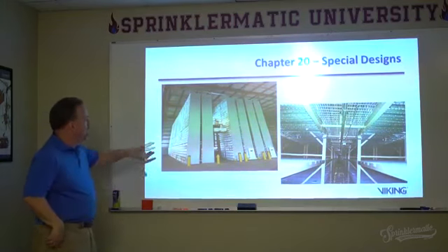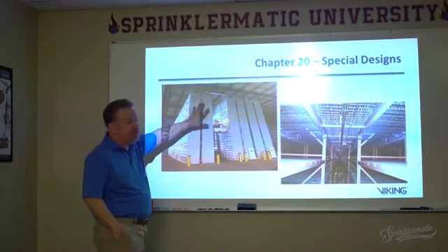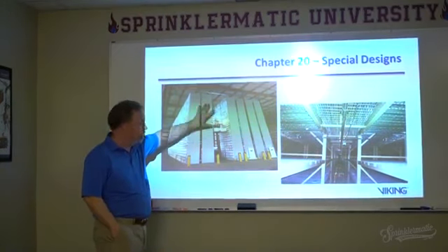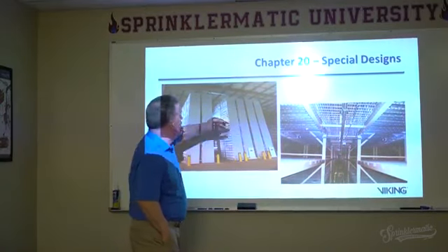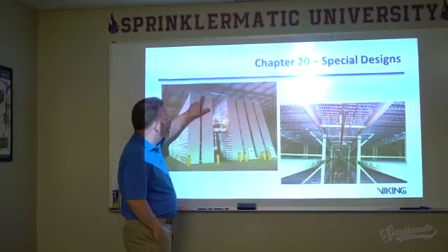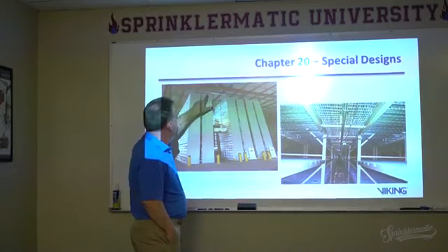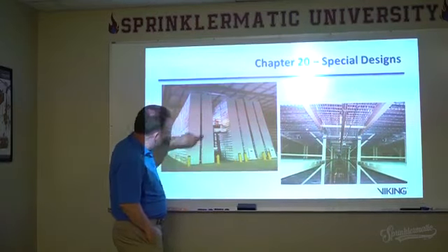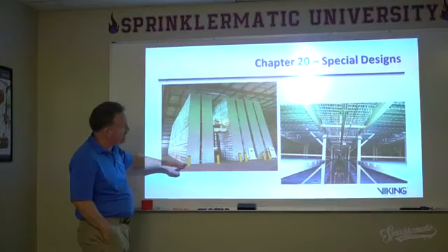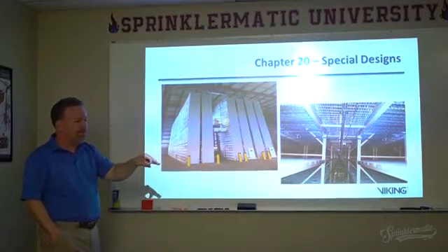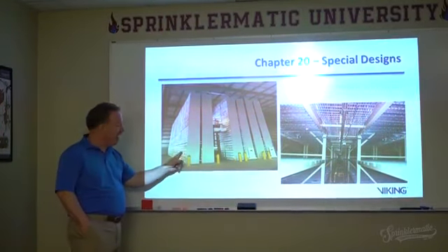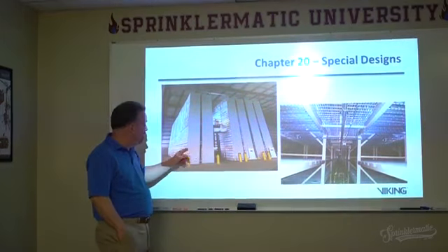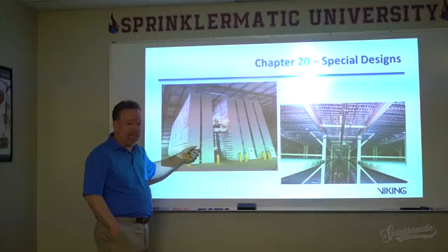Typically, these are protected by ESFR sprinklers as the design criteria. ESFR sprinklers protect this commodity at 40 psi, I think it is. The other interesting component here is that the support structure for this unit is required to be hollow tubes. If I get a fire going down here, this is pretty lightweight steel. You get a fire going in here, you can easily collapse this thing by weakening the steel.